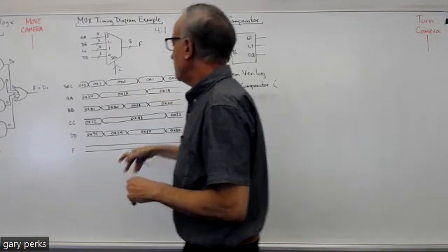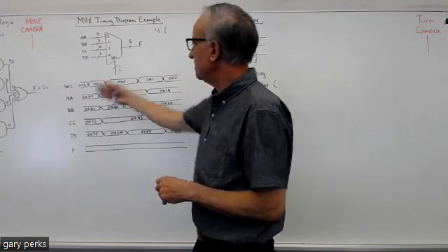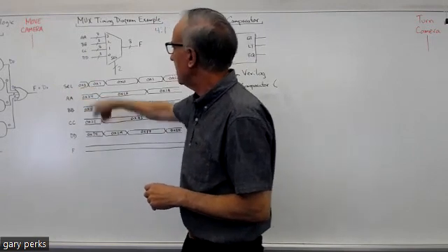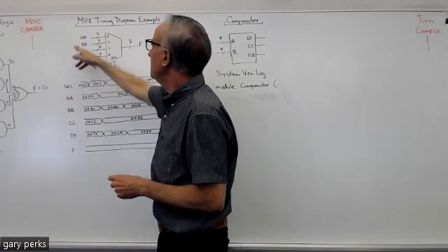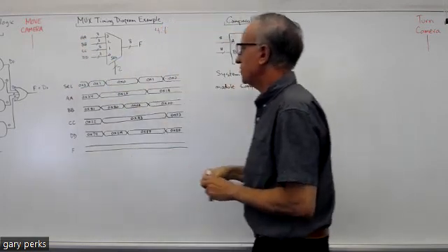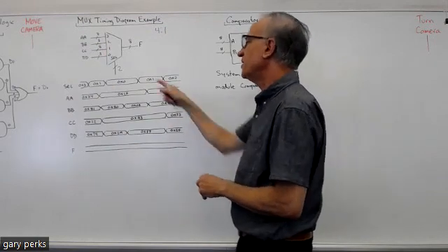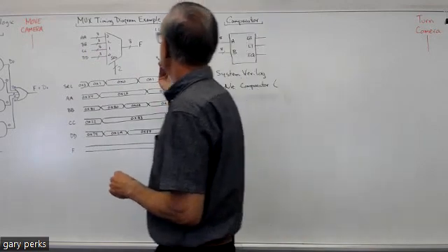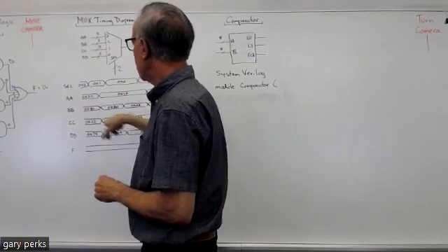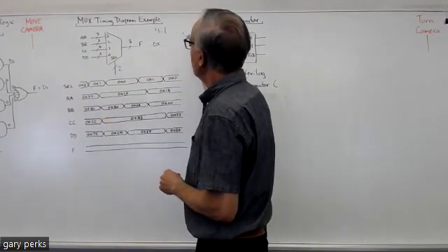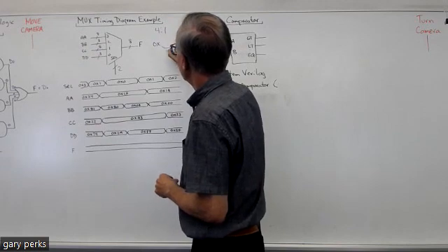All right, so what we're going to do here is come up with what the output is based on these values for select, and then the data. It's labeled AA, but it's still data. So we've got these 4 data inputs, and we're going to determine what data gets to the output based on these select values. Now, one thing you haven't seen before is this 0x. You know, there's 0x3, 0x24, and so on. 0x means that what follows is in hex.